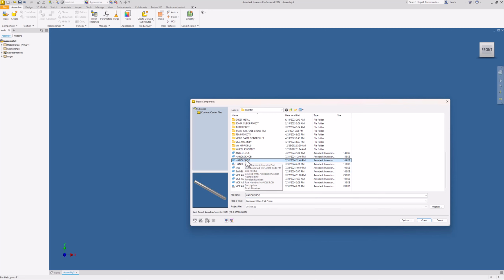And also the book says that this hole needs to be rotated 30 degrees from the flat plane here. So to get that done, let me zoom in a little bit. I'm gonna go to my screw. I'm gonna turn on the options here, or open a folder where I can see. So I want to click this XY plane. I'm going to turn on the visibility of it.